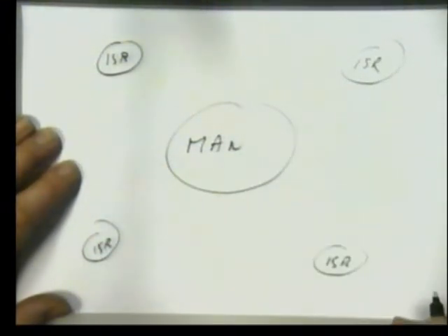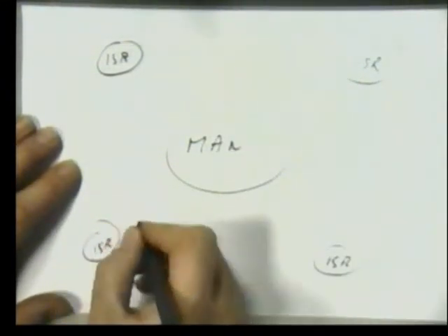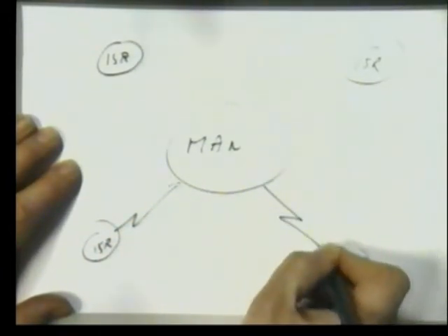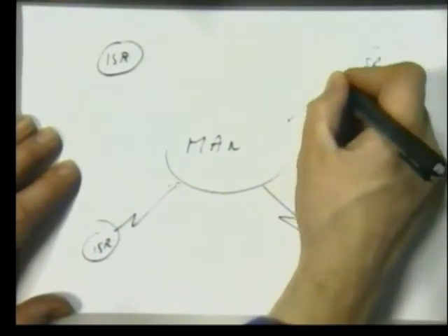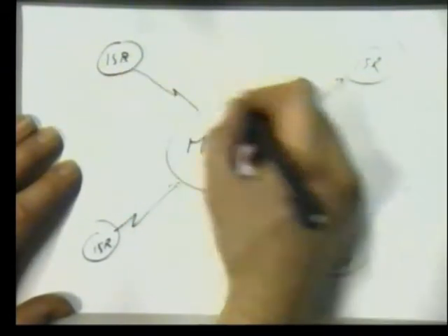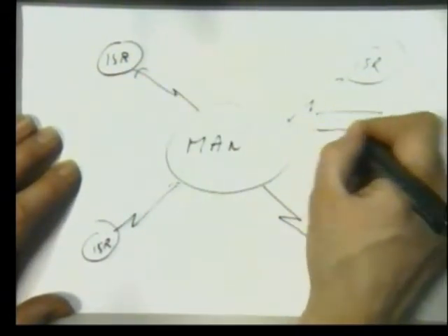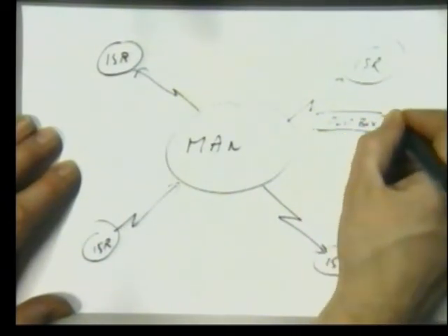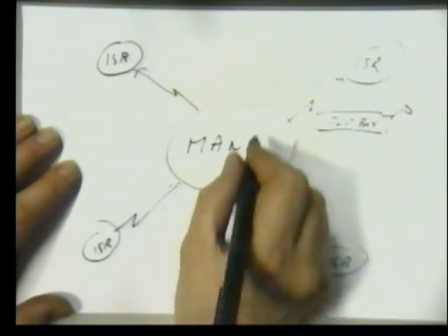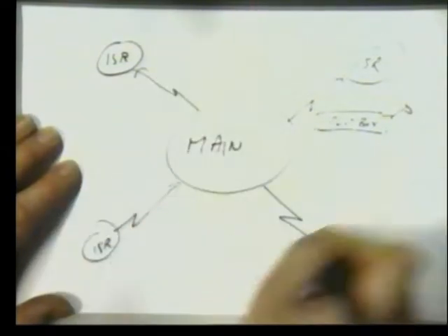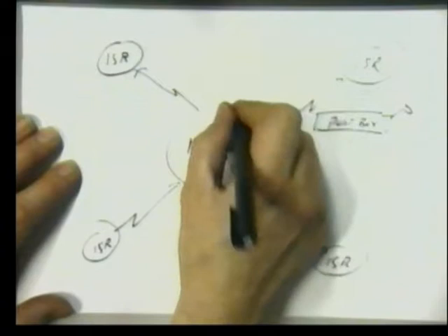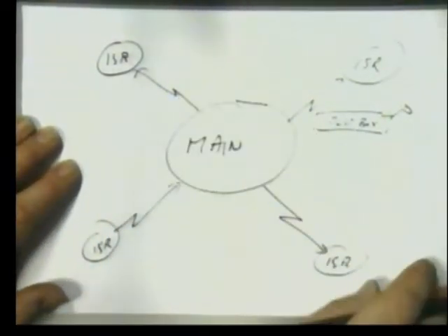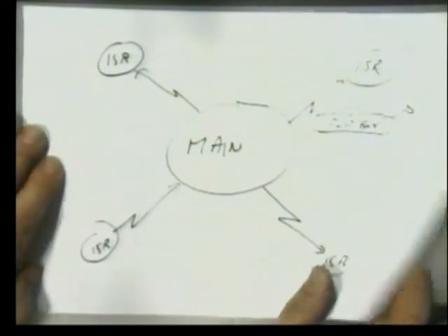ADCs, timers, external events, power fail, and these are all communicating with each other, not directly, but via data structures that involve the use of post boxes and simple semaphores. So we have parallel processes happening at any time, we don't know when they're going to happen, and post boxes that pass the data backwards and forwards between them.